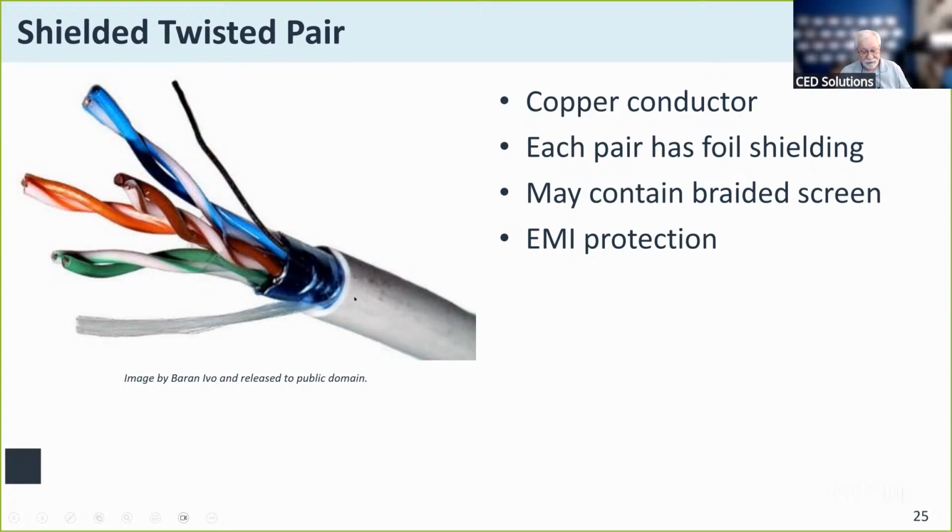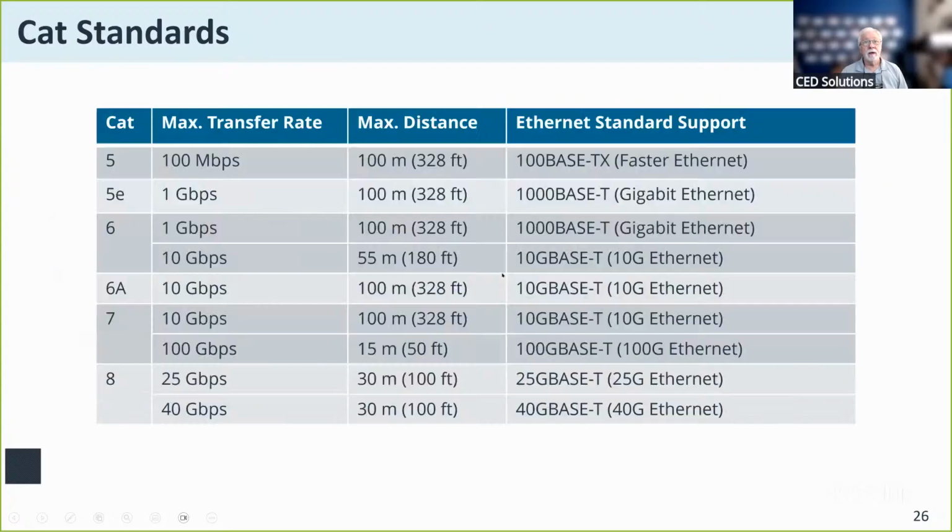So this is the next version of it, the shielded twisted pair. Now that shielding there gives you additional guarding against what's called EMI, electromagnetic interference. There's also shielding against radio frequency interference, which can interrupt and interfere with the signal going down these as well. In some of the higher quality and higher priced versions, in addition to the aluminum wrapping grounding around it, some of the higher ones will have the braided copper, much like coax cable. Pretty expensive, but very well grounded, good protection on EMI and RFI interference.